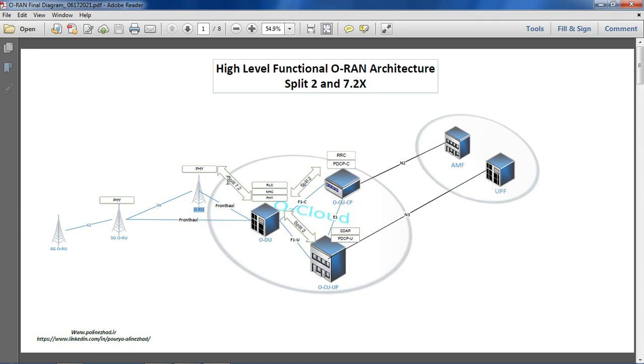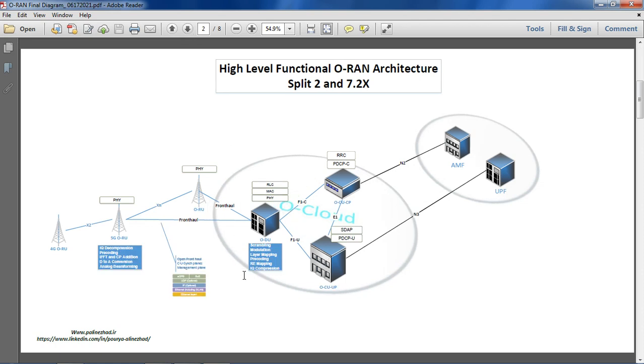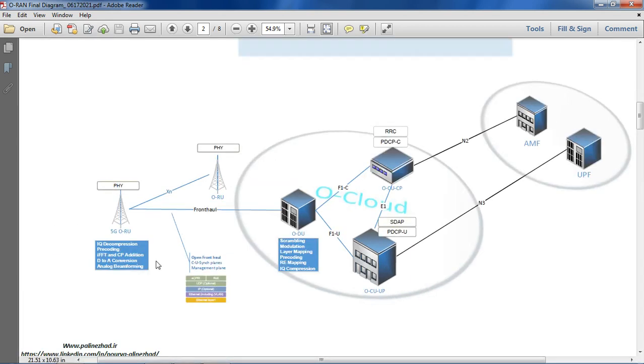This image shows the O-RAN Alliance chose option split 7.2 because this is the optimal splitting point in terms of RU complexity and transport network loading. And as we see in the Xilinx presentation, it's somewhere within the physical layer, and we will add more details in the next page. So let's go to the next page. Here, let me zoom in.